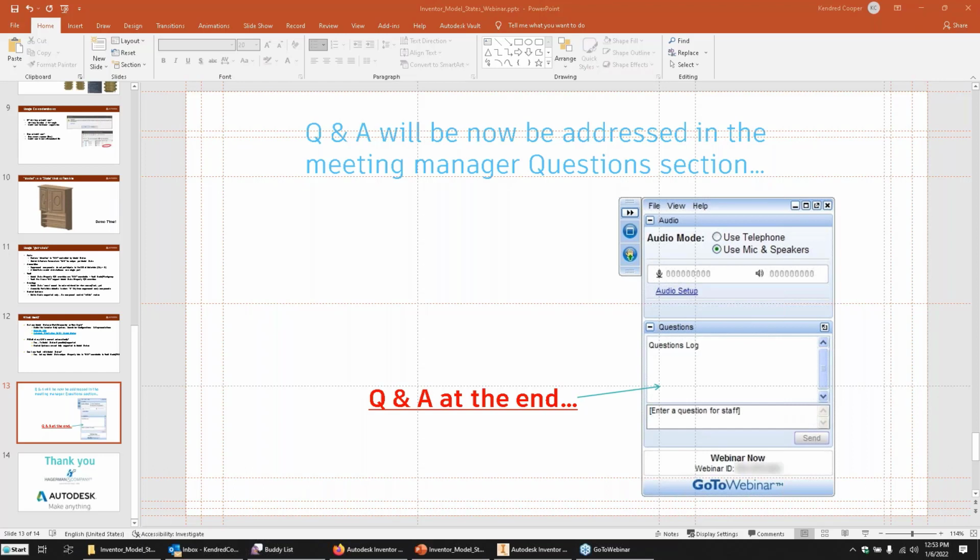Is there a limit to the number of model states you can create? Not that I have seen. There's no documentation from Autodesk that states that. And in learning this and just playing around with the various options, I think I got up to around 25 or 30 model states inside a one-piece part, and it didn't have any kind of problem with that. Is this in reference to the iPart limitation, where a component could have about 120 before it starts to choke Inventor? If so, I would imagine that the model states are going to handle the data much better, because it's not the same level of information. It's just a value change. I would agree with that 100%.